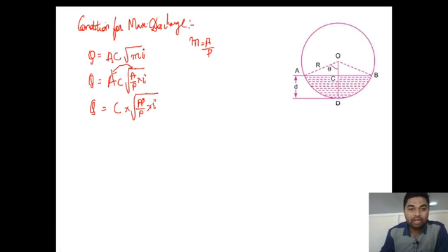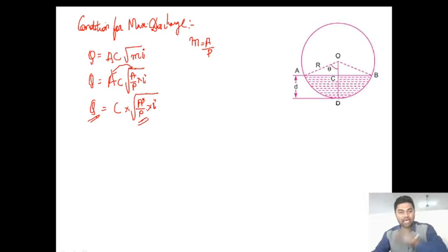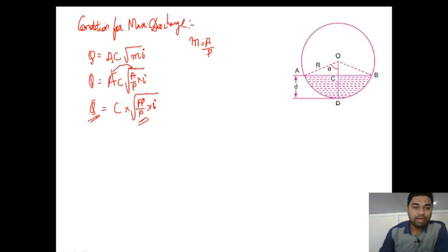See this A, if we go inside the under root, it becomes A square. A square into A is A cube. So we will be getting the value of maximum discharge if A cube by P value is maximum. We will be getting the maximum discharge when A cube by P value is maximum.